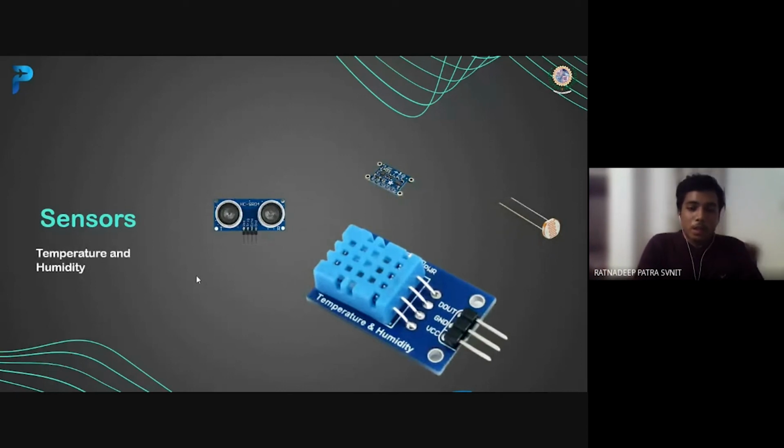Next is the temperature and humidity sensor. This basically detects the temperature and humidity of the surroundings. The sensor shown here is the DHT11 sensor, and it has 3 pins. One is the VCC 5 volt pin, the other is the ground pin, that is the 0 volts, and the third pin is the one that outputs the data. It outputs data of temperature and humidity in the form of serial communication. So this was the temperature and humidity sensor.